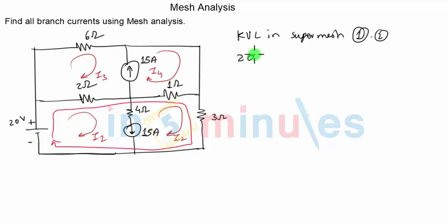So it is 20. Next is 2 ohm resistance. Through this 2 ohm resistance, the current is I1 flowing towards right and I3 which is flowing towards left. So if I take a current flowing towards right, which is same as I1, then that current will be nothing but I1 minus I3. So I can define current flowing towards right hand side as I1 minus I3. So because we are also traveling in the right hand side direction, the drop will be negative. Minus 2 is the resistance and current we have taken is I1 minus I3.